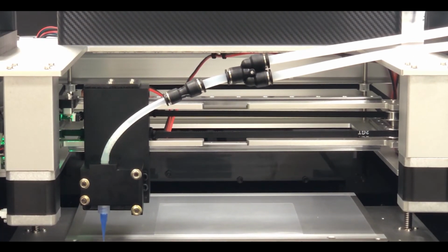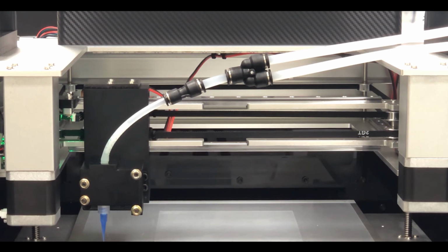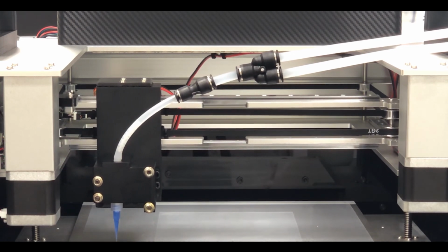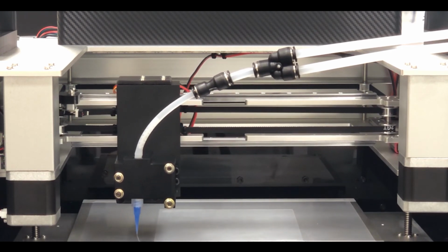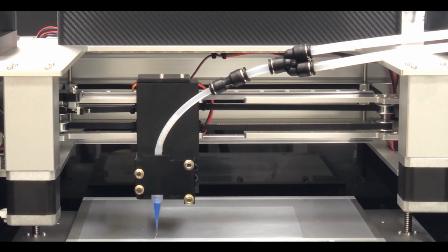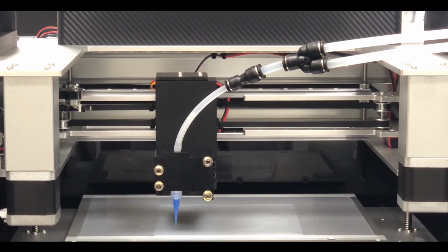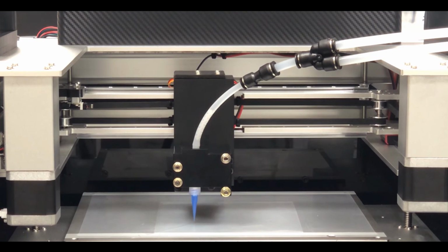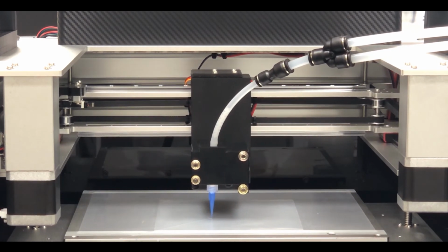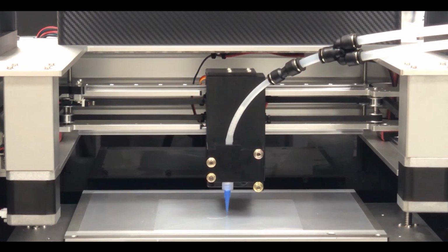After the slicing is done, make sure the silicone is at the end of the nozzle. Then before printing, go to Manual Control page and do pre-extrusion of material. That is, click on the positive value of extruder.